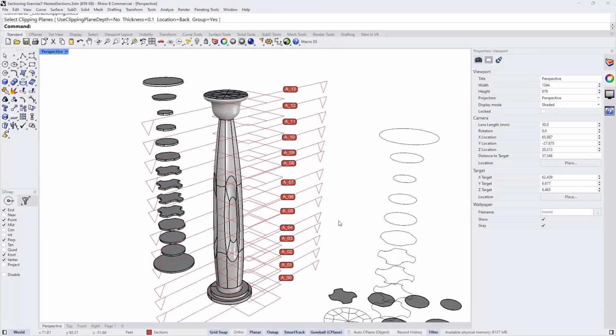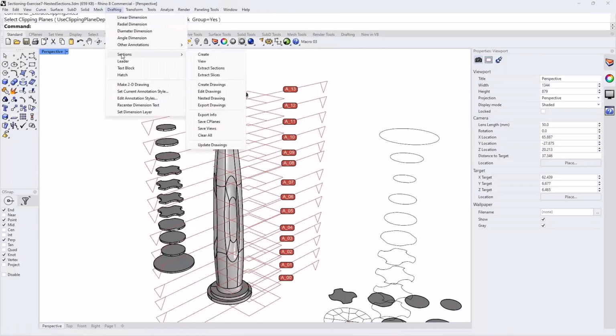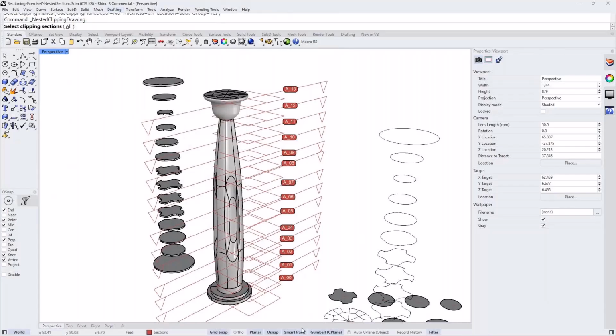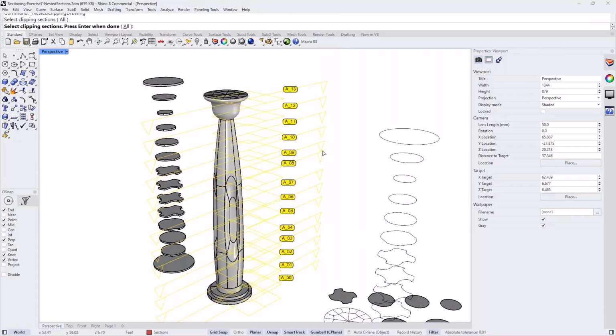That's kind of interesting, but my question is this: why don't you just extract the sections themselves like we did instead? Well, if you extract a section and then you're going to laser cut out of a material that has a thickness, and the portion of your part above that section is larger, then you're going to have a slice that cannot be materially subtracted down to the taper that you want if we're doing subtractive manufacturing.